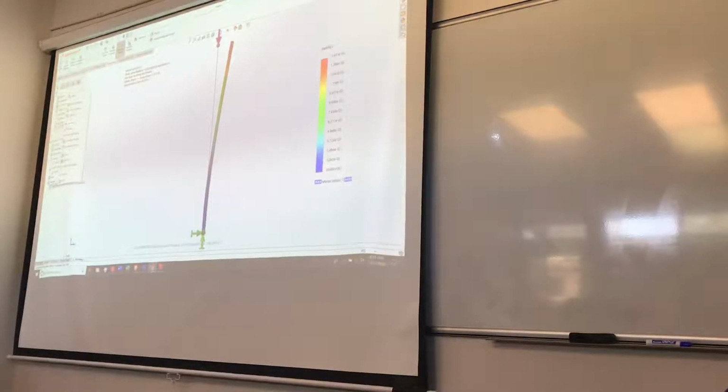What's that? Oh, never mind, that didn't work. Actually, let me do the user defined properties. Oh, that's because I didn't define any of them. So let's go get 5 or 6 of them. Under the buckling, under the settings, let's go get some more modes. Under properties, you can say the number of modes, and that's why it can't find any, because I only defined one. Okay, how many modes? Oh, I just picked a bunch of them. Okay.